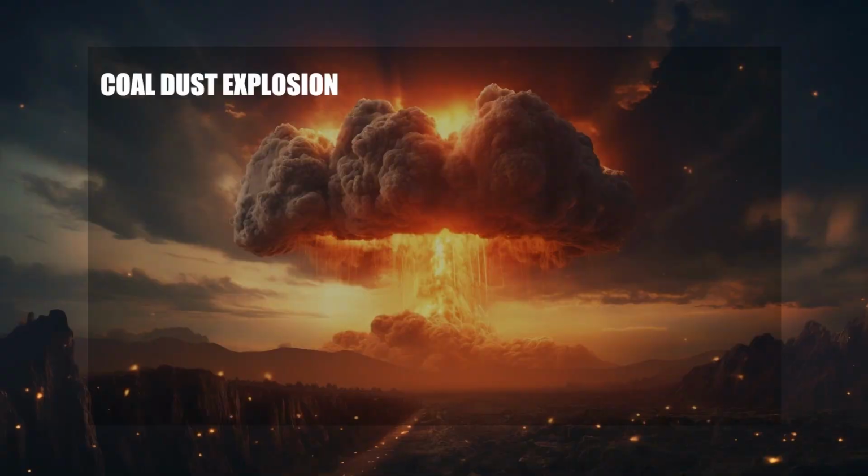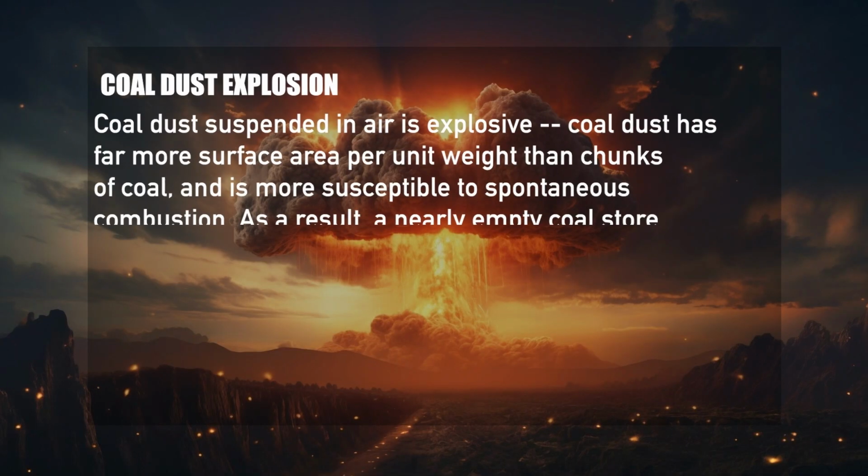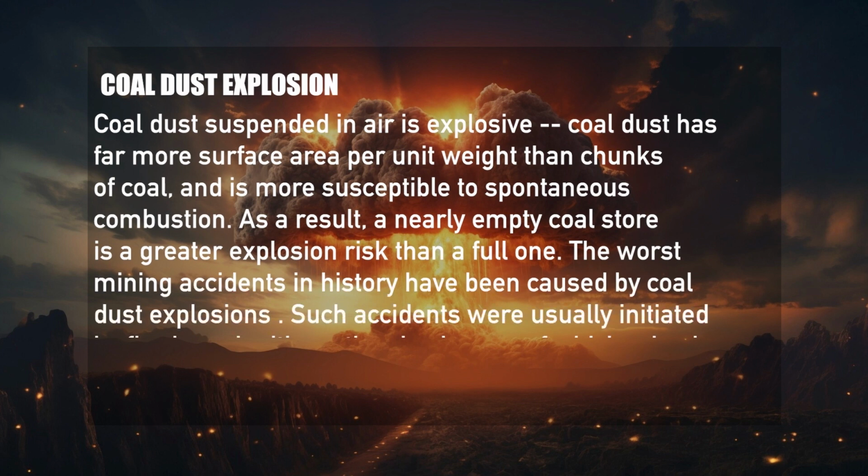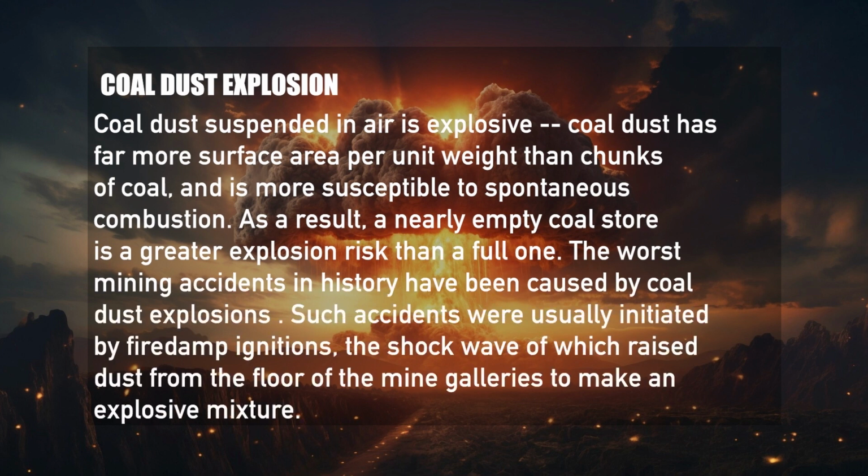It means a coal dust explosion can only take place if there is availability of coal dust, the ability to mix with air to form a cloud, and a sufficient source of ignition. Coal dust suspended in air is explosive. Coal dust has far more surface area per unit weight than chunks or fragments of coal and is more susceptible to spontaneous combustion. As a result, a nearly empty coal store is a greater explosion risk than a full one.